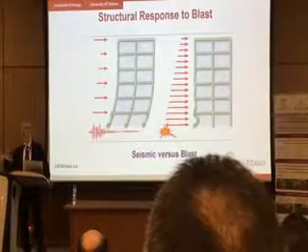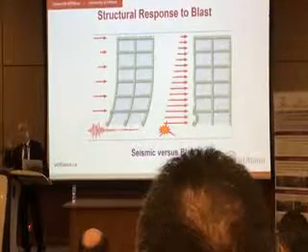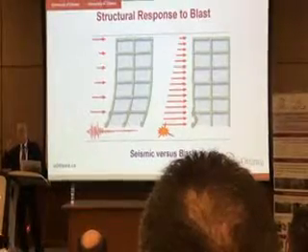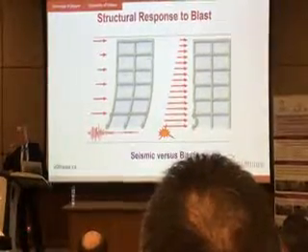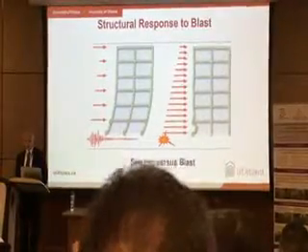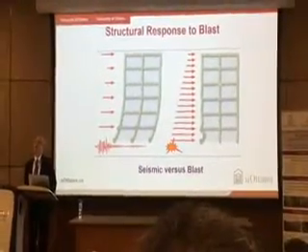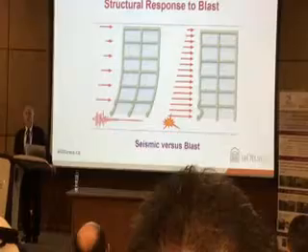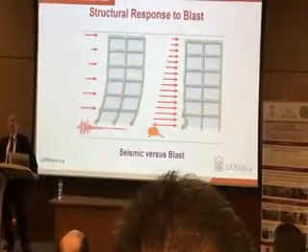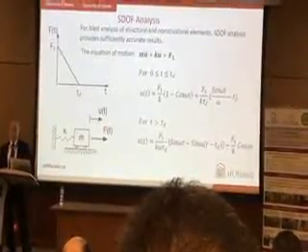So the entire building is not affected because they don't talk to each other. But if you look at the period of a facade, if you look at the period of a column, they have very high frequency, low period. So now the period of excitation starts affecting facade elements, not the entire building. And that's why I've shown you all those pictures. The facade came down because these are the high frequency members of the structure that are influenced by blast loading.